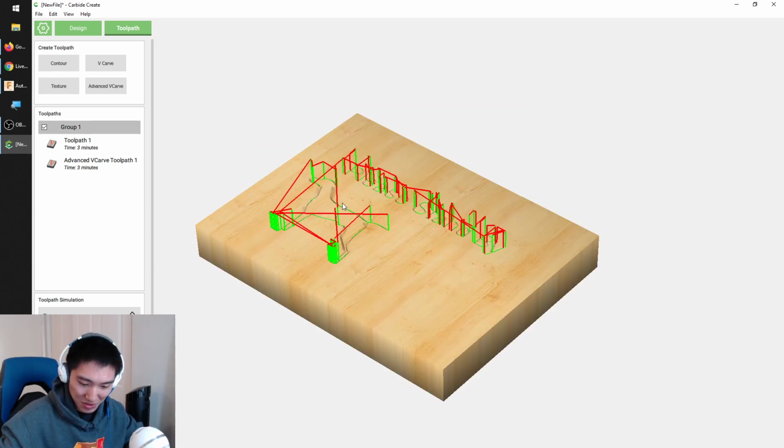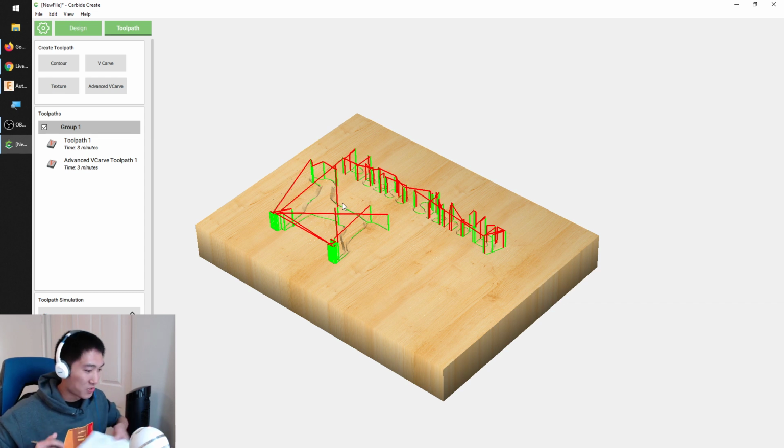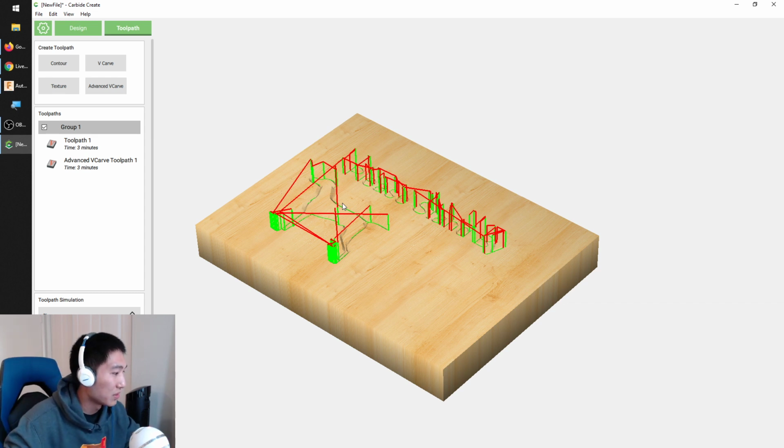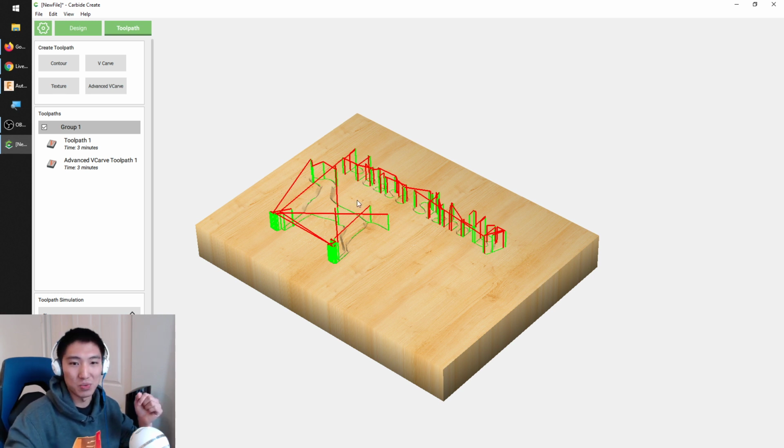Let's see. I had a couple questions from the forums that I wanted to address really quickly. Julian asks about belts and calibration and my thoughts on that. So the way belts work on the Shapeoko is there are 2 anchors on either side, and there are M5 screws that go into those anchors and pull the belt.